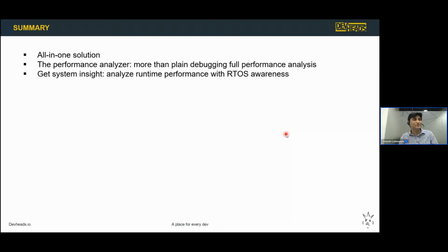That's why I showed you that you can track all the information in the FreeRTOS window of the Ozone software. You can see the priority live, the status of the tasks, mutexes, counts, even how much memory is consumed, right?